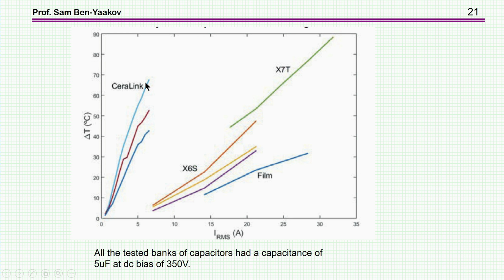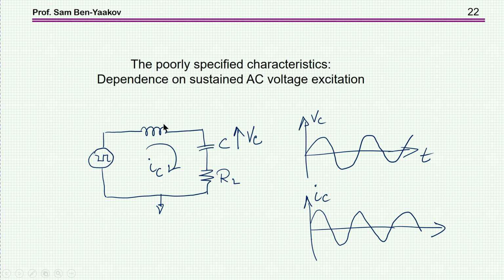And you have to go to very high, as we've seen, 120, 150 degree to get the benefit of the low ESR. Now, if you have thought that this is complicated and bizarre and too many parameters and too many dependencies, well, wait until we talk about the AC behavior of the ceramic capacitors, which is even more complex.